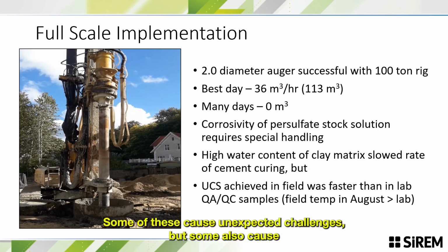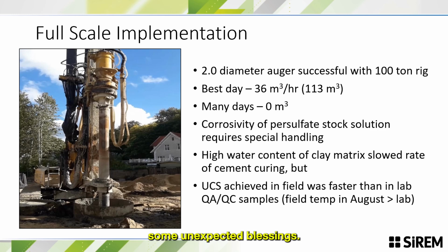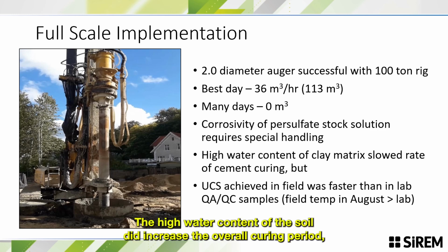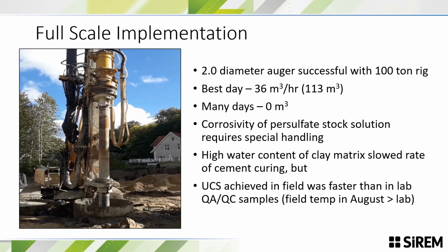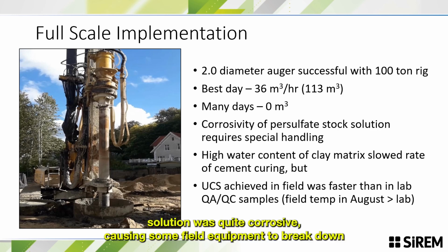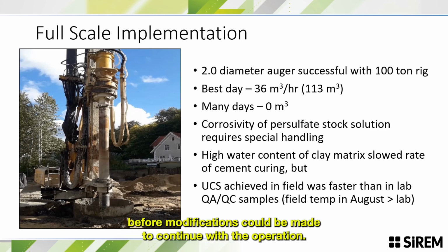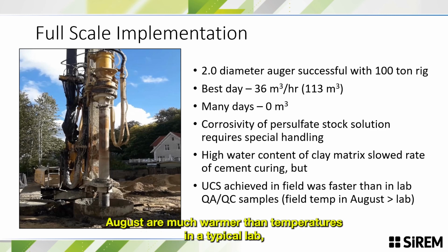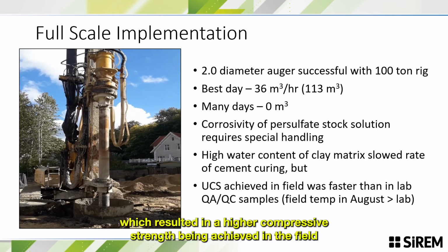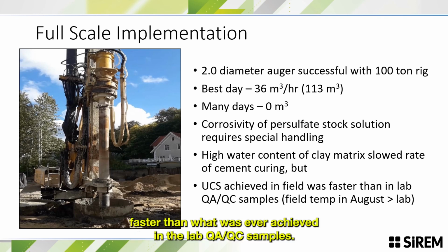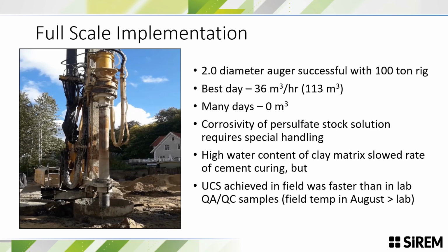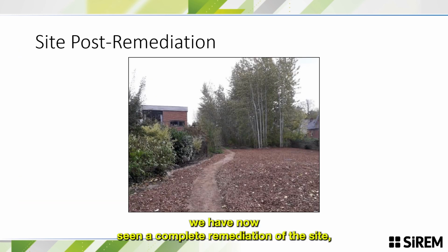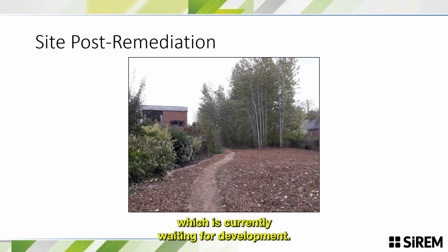Some of these caused unexpected challenges, but some also caused some unexpected blessings. The high water content of the soil did increase the overall curing period, and the persulfate solution was quite corrosive, causing some field equipment to break down before modifications could be made to continue with the operation. That being said, the temperatures in Denmark in August are much warmer than temperatures in a typical lab, which resulted in a higher compressive strength being achieved in the field faster than what was ever achieved in the lab QA/QC samples. And as a result, we have now seen a complete remediation of the site, which is currently waiting for development.